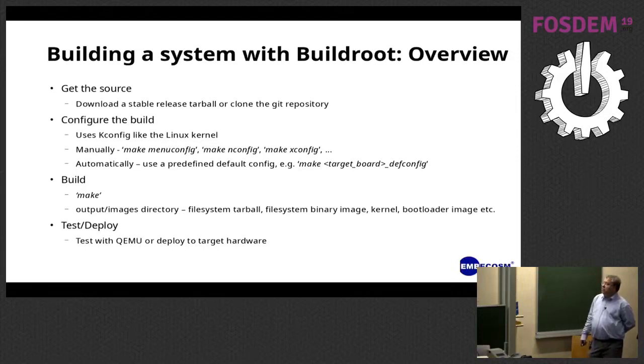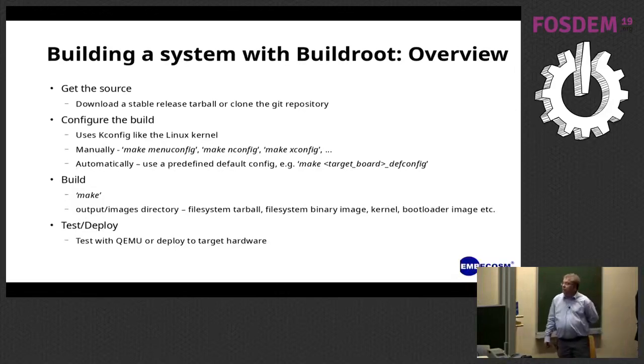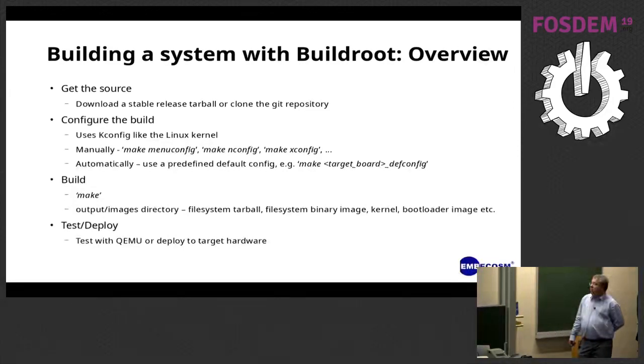Building is just as simple as running make, and then once the process is completed, you will find that you have your files ready to deploy in the output images directory. That can be a tarball, an image, or a kernel and bootloader, depending on what's been specified for your target. And then the final stage is to test or deploy. In my case, this was testing with QEMU, but it could be that at this stage you copy your files to an SD card or memory device for your target board and then run.